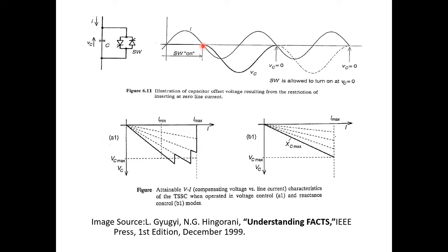At that time, I would like to turn off the thyristors, and the voltage will double up to the level of 2 cycles, one negative cycle and one positive cycle. The entire capacitor voltage will double; 2 cycles it has to cover. There again VC becomes 0, and at that time the thyristors will turn on again. Up to now the thyristors are in the off position. That's why we come across the total voltage across the capacitor.